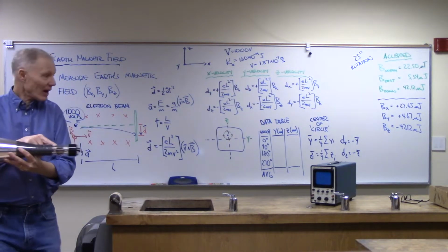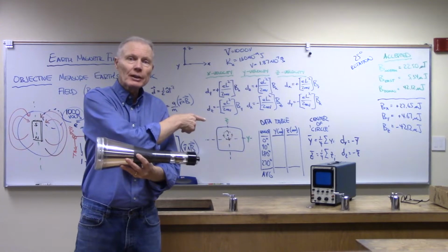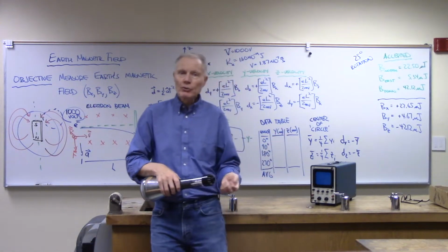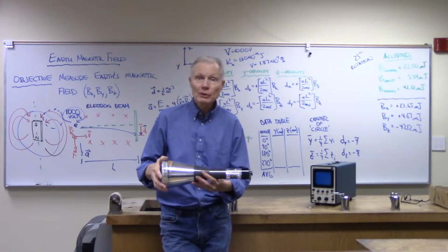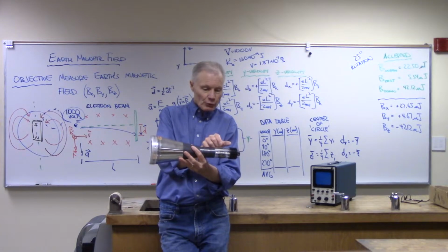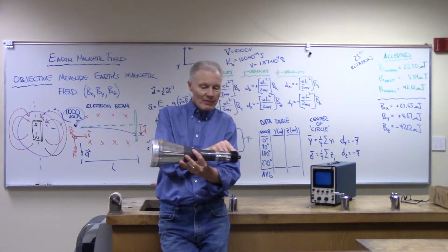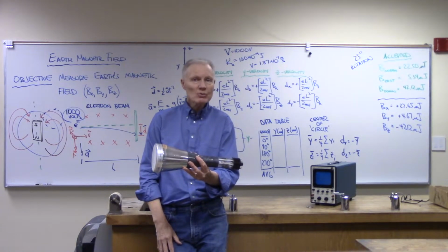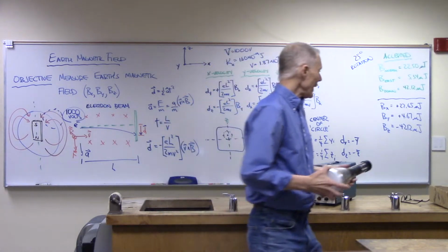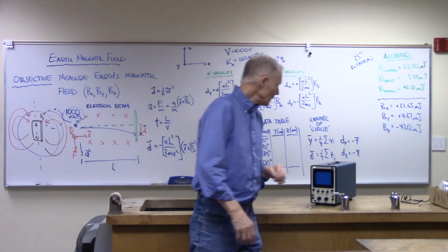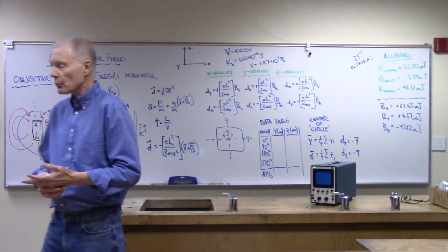What they do is they have a vacuum tube inside, where at one end of that tube, there are high voltages that are generated. It turns out that our oscilloscope uses 1,000 volts to accelerate the electrons. And so there's a 1,000-volt region concentrated at one end, and then the electrons pick up speed, and then the rest of the way they mostly just drift. So what happens then is, let me turn on the oscilloscope and let's see what it looks like with the electrons hitting the screen.